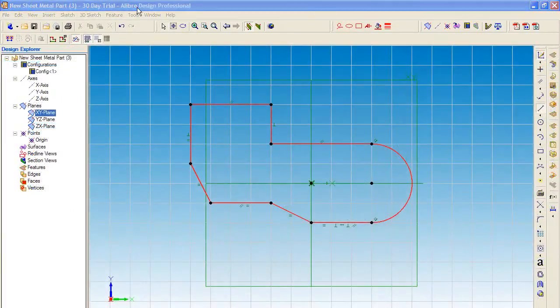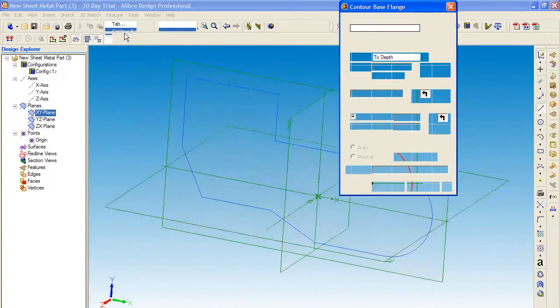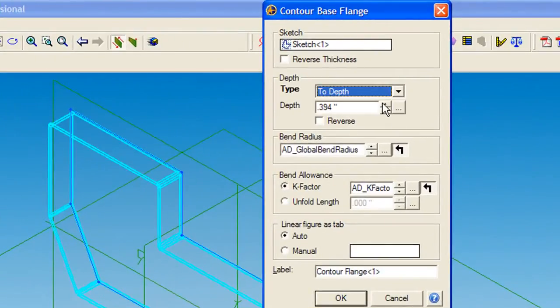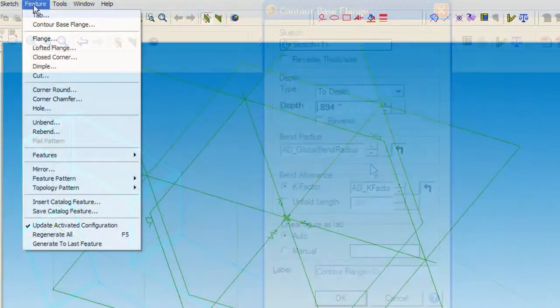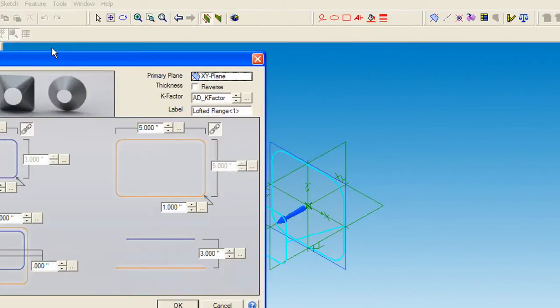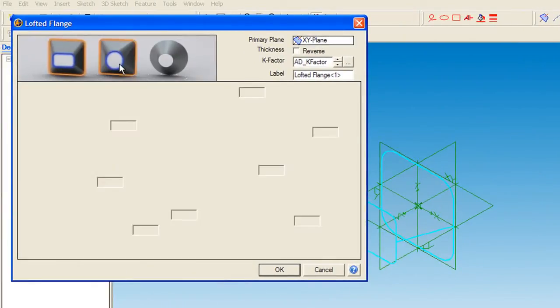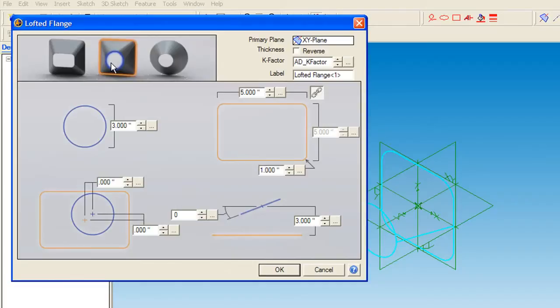Now let's get into the sheet metal mode. For sheet metal, V12 lets you draw a 2D profile, then convert the profile into a sheet metal part through this dialog window. Also new here, you can create lofted sheet metal parts that taper in one direction. But it's a pretty restrictive way of creating them, I thought. Ideally, I would want to be able to draw the two profiles to use as a bottom and at the top of the sheet metal part, then have the software connect the profile with a certain thickness of wall.